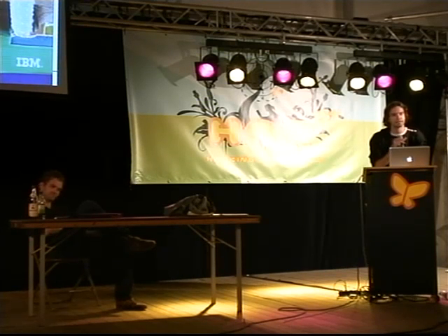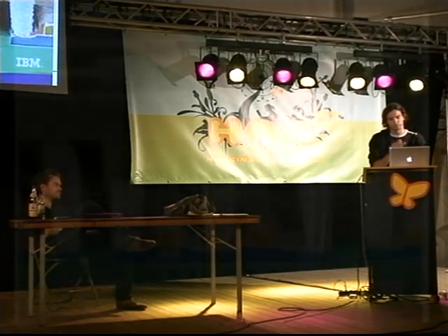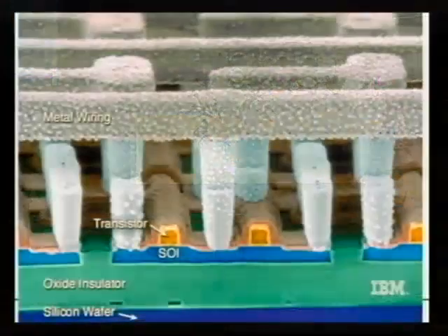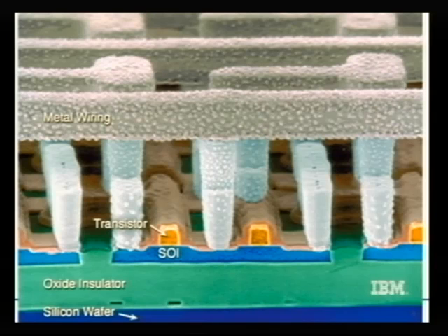To understand the next steps on the next slides, first of all, what does such a chip look like? We start at the bottom. It's a bare silicon wafer, and on top it begins with a transistor layer. So there's a gate, source, and drain over here, and those transistors are connected on higher layers, called the metal layers, with metal wires.